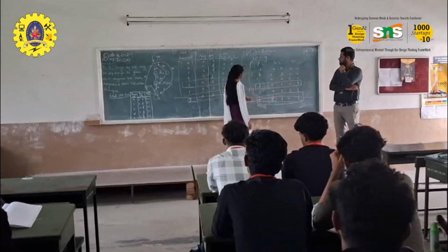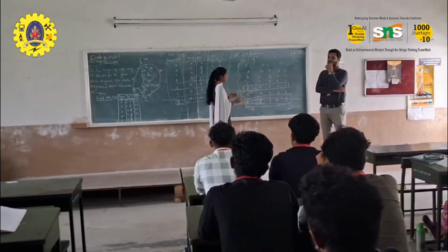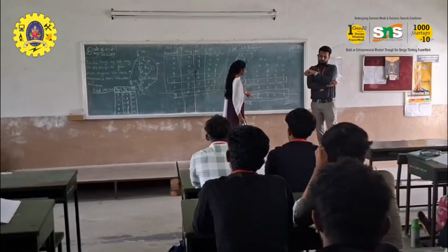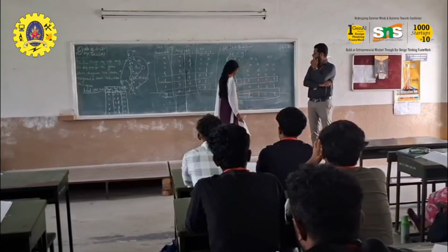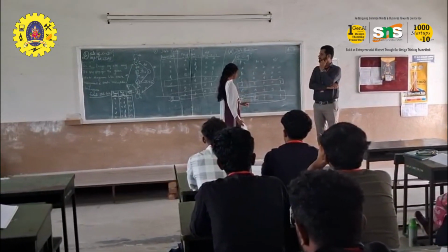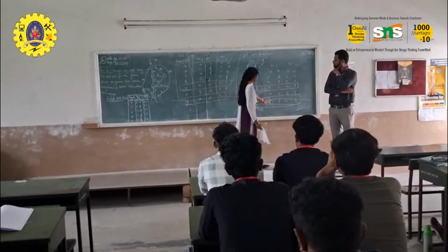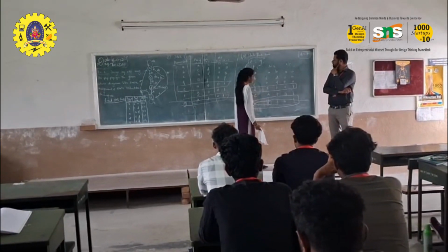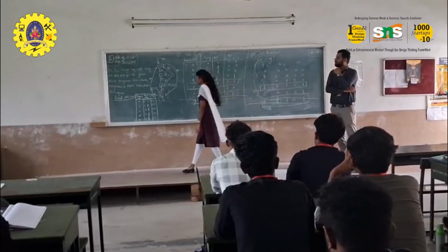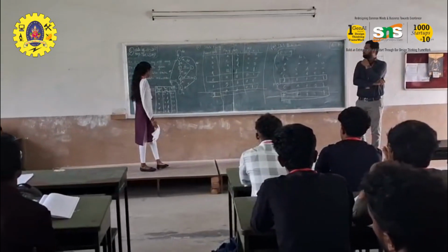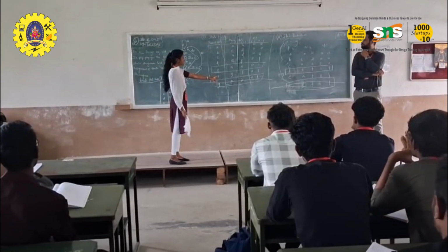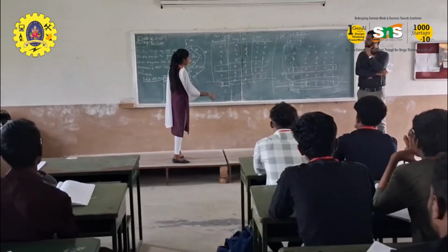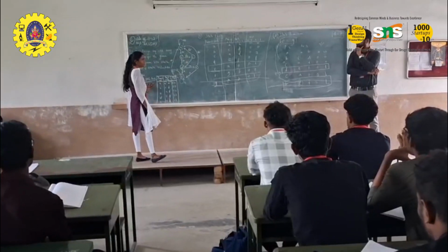Next we follow the same steps. D and F are both the same state, since the next state and output are both the same. Now we want to eliminate any one state. D and F are both the same, so D is equal to F. Next we go for the final state. We eliminate the F state and replace F with D. So this is the final state.